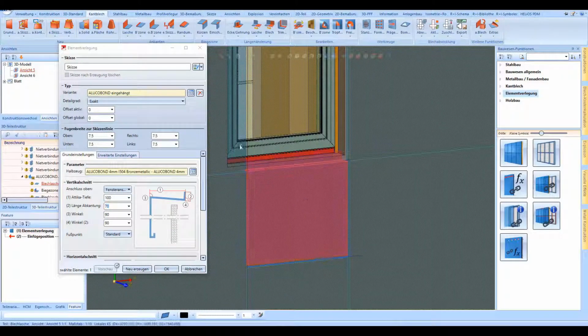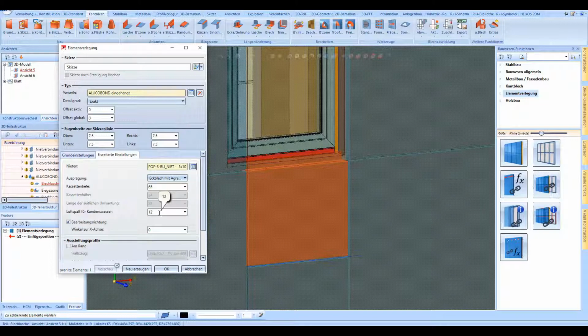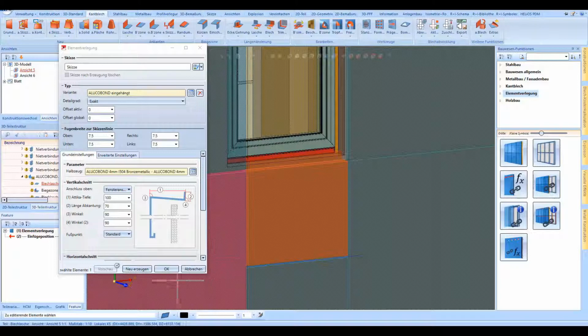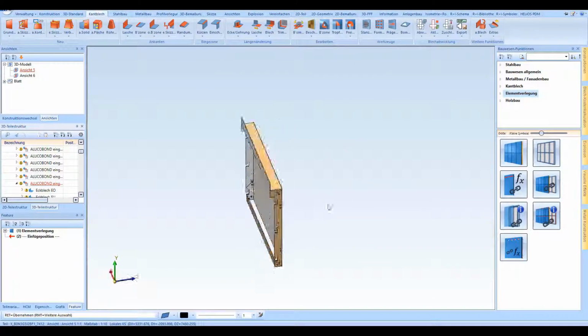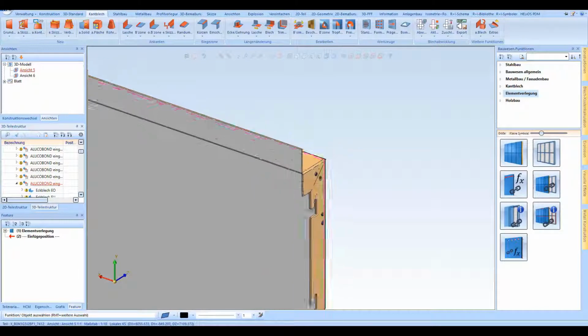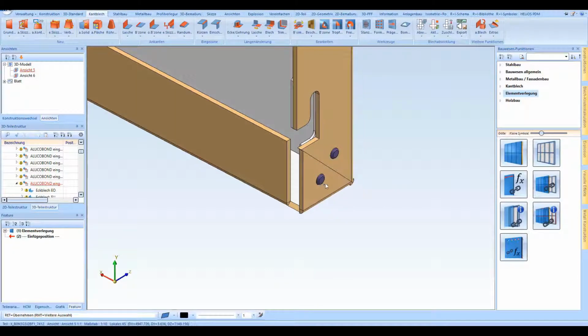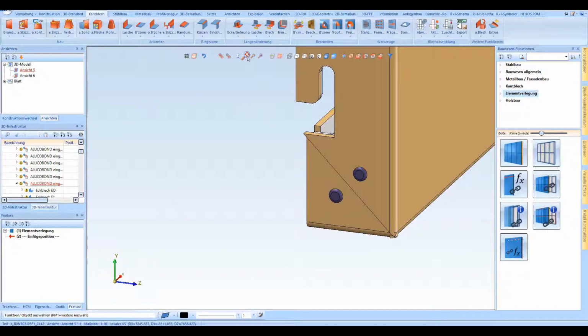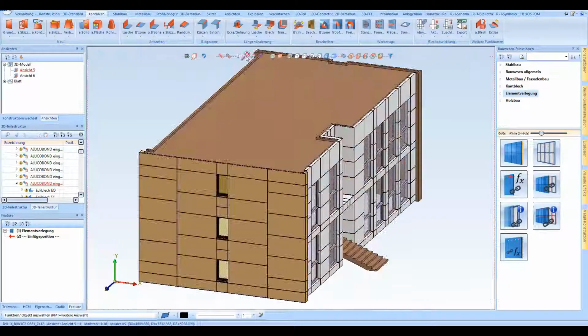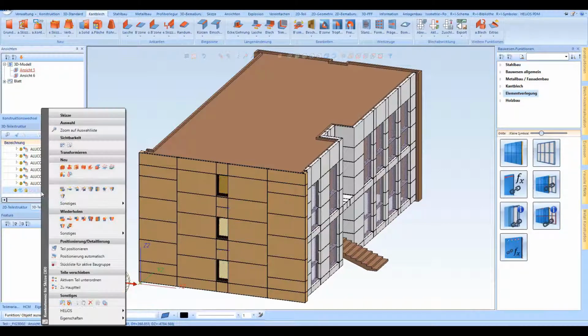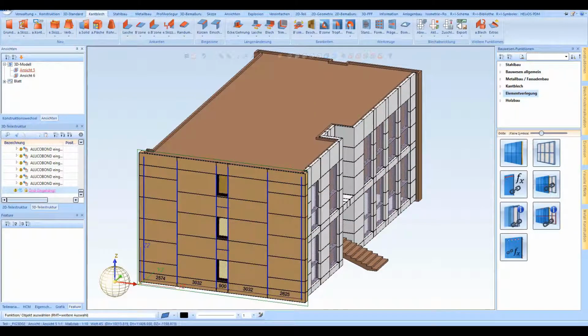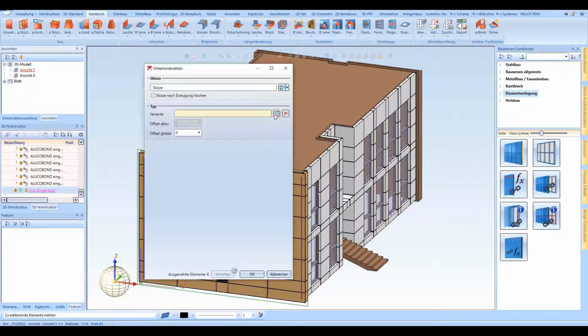In this area we would also define a window connection, include a level of detail, and via extended settings we can define a clearance for condensation. Now we can see all parameters we defined on this tray panel, including the clearance. In the next step we would create the substructure via catalog as done before and have a look at it afterwards.